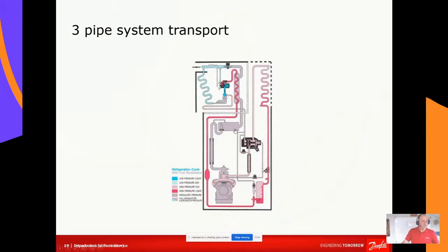Challenge on what they've done on here is quite good. They've actually taken a tapping off here that puts a little bit of hot gas into the liquid receiver to keep the pressure difference up, so the system keeps running. Now, these evaporators are only fairly small, so they don't take that much defrosting. So it can be done, but the control scheme and all of that needs to be very, very good. So I'm just going to stop sharing the screen now and go back to the questions. Hope that sort of answered that question a little bit.